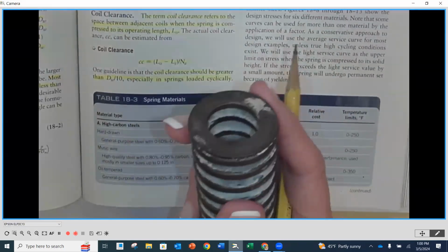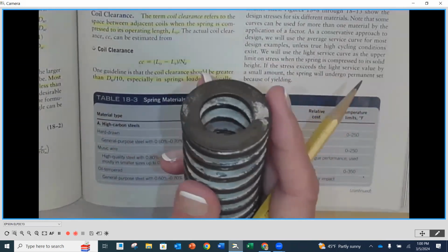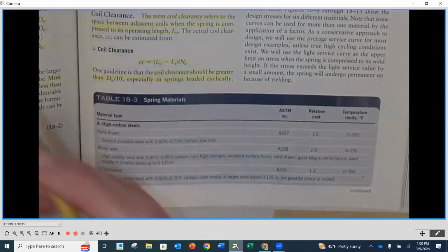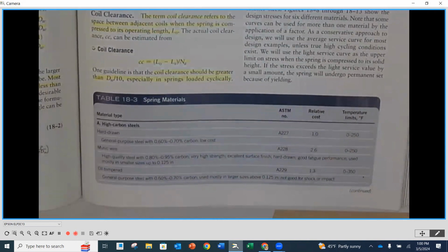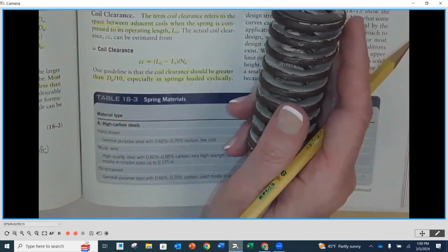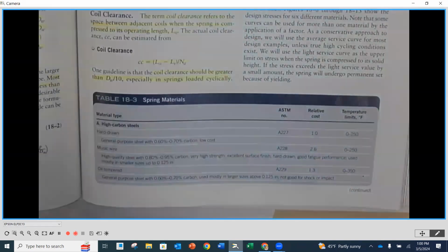But if you're in the food grade industry, steel that is uncoated, probably not so great. Now we've got to look at maybe some other alternatives like stainless steel or other coated types of springs, because you can't have something corroding around food. Okay. Other industries as well, depending on the environment that you're in. If there's a lot of humidity, steel might not be a great choice. You might have to go with something else, or at least coat them so that they don't rust. Okay. So a lot of different options.